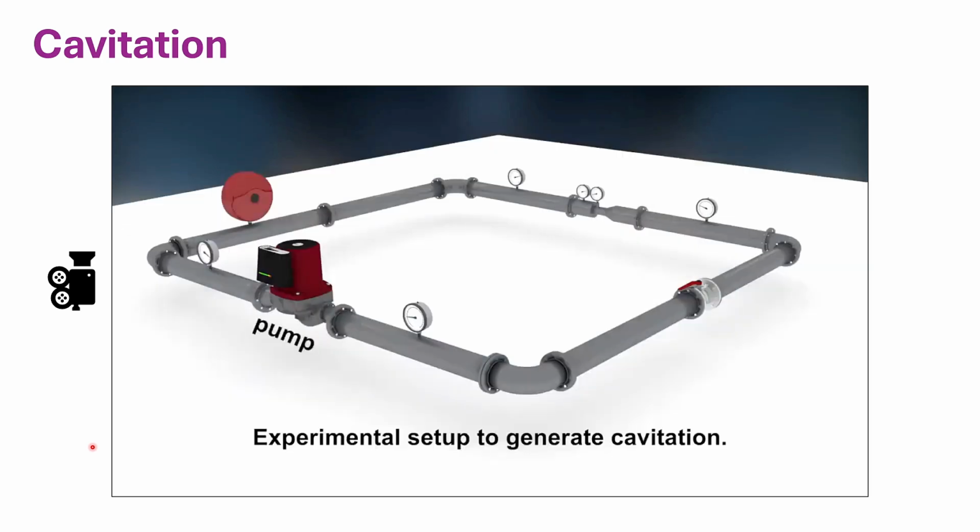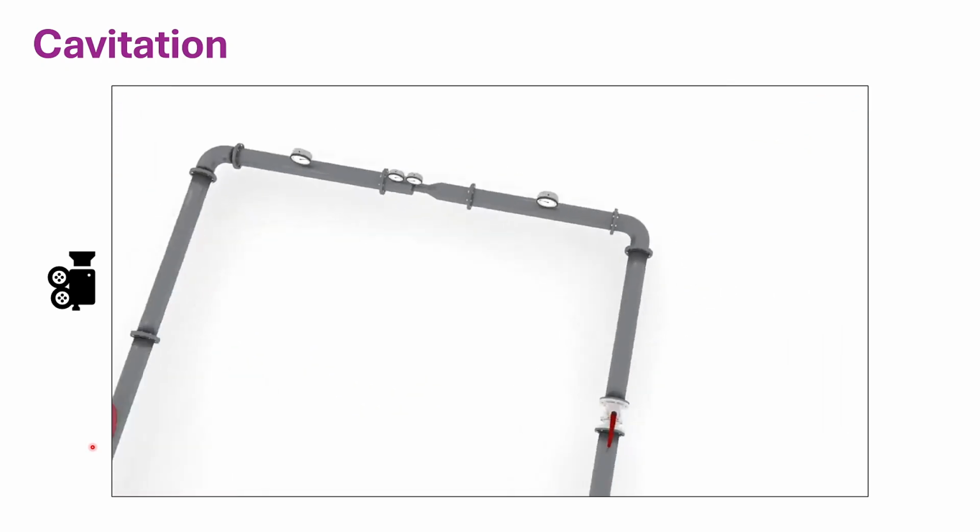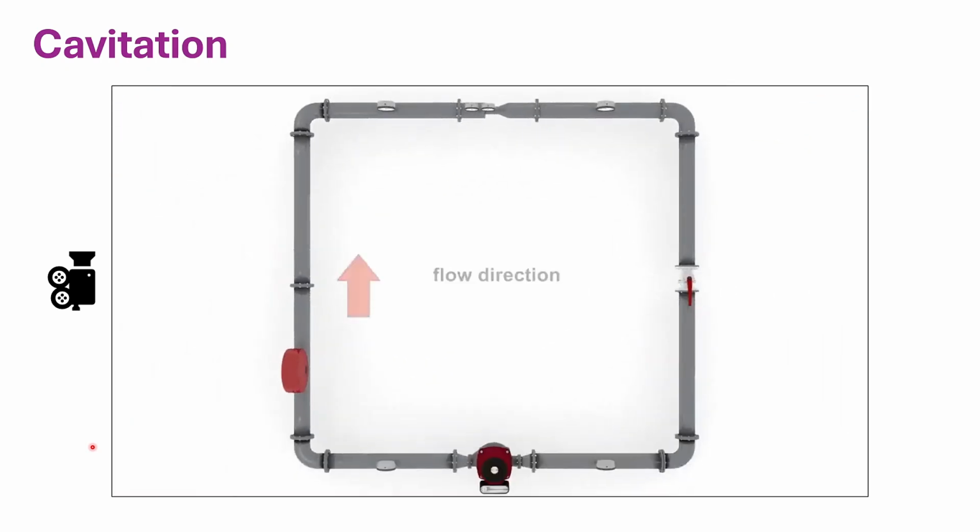When pumps circulate water through piping systems, cavitation can occur where the pressure is lowest, at the inlet of pumps and in narrow pipe sections. If the pressure at the inlet of a pump is low and approaches the vapor pressure, cavitation can occur at the pump impeller as we have seen it at the ship propeller. The pump can deliver less water because the cavitation bubbles occupy a part of the cross-section where the water should flow. Damage from collapsing vapor bubbles will be shown later.